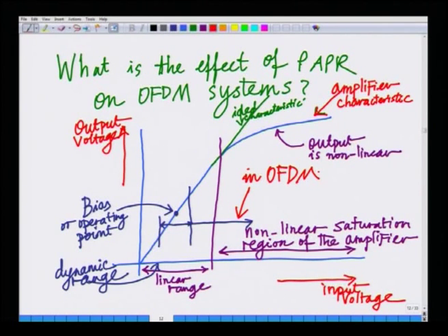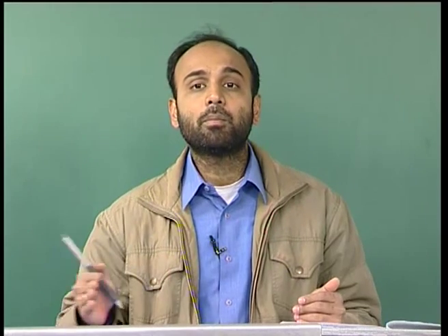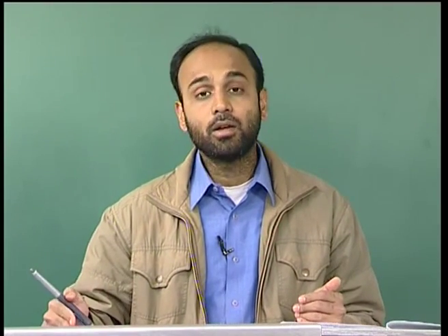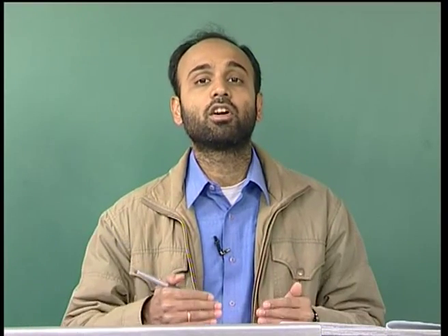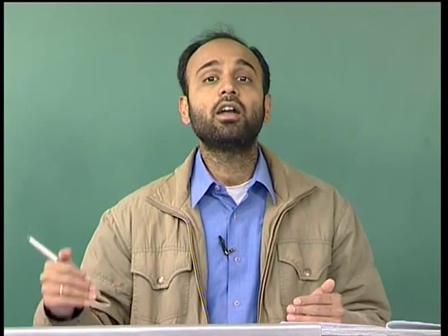The problem in an OFDM system is that we have non-ideal amplifiers in practice with a limited linear amplification range, and the swing of the peak power can be very high compared to the mean. Once the amplification is non-linear, all the properties of OFDM cease to hold. That is, orthogonality is lost, there is going to be severe intercarrier interference, and so on.